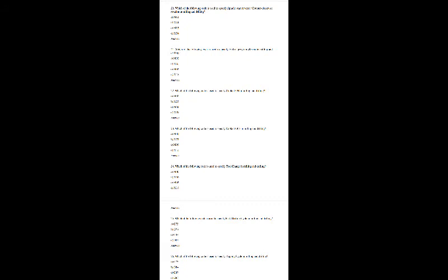In bracket it is reset is there in milling and drilling. So the options are option A M30, option B M05, option C M02, option D M18. Okay, so here the answer is M30. This M30 code is used to specify end of program or reset in milling and drilling. Now let us see the next question.